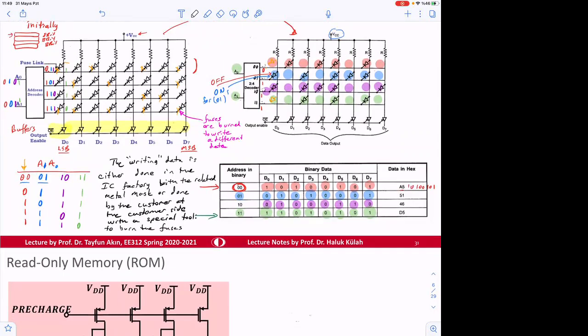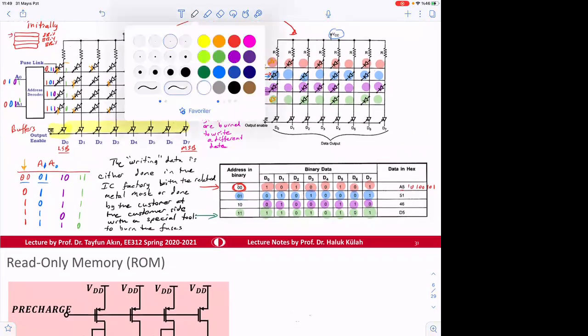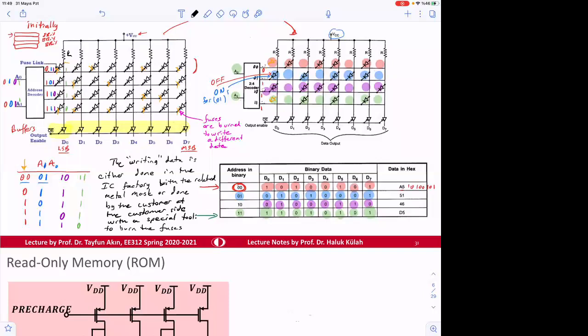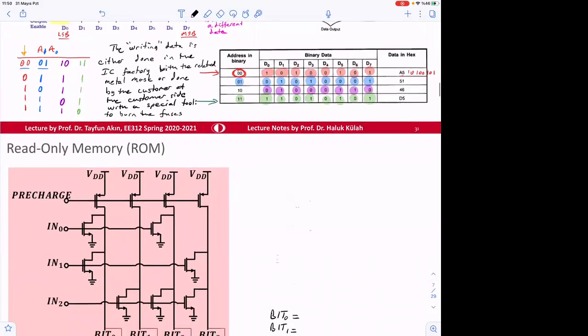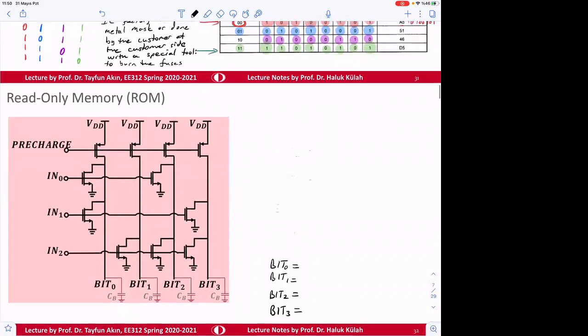This is maybe the older method, where there used to be resistors, R, but manufacturing resistors is difficult. And it dissipates a lot of power when the output is 0, because the voltage there is 5 volt divided by R, which is large. So people decided to implement the same idea, but differently.